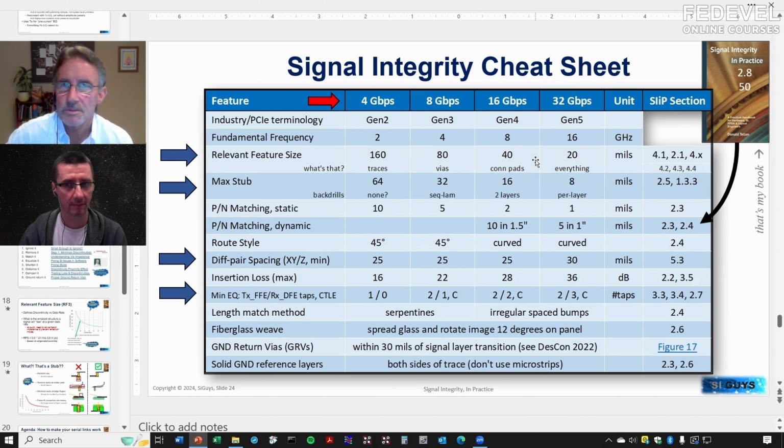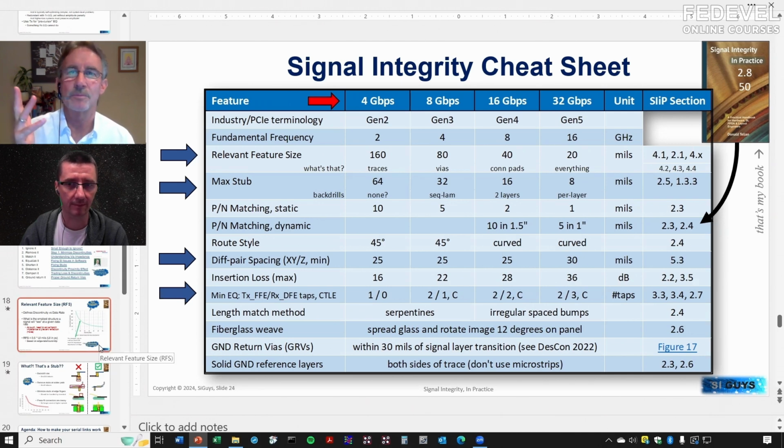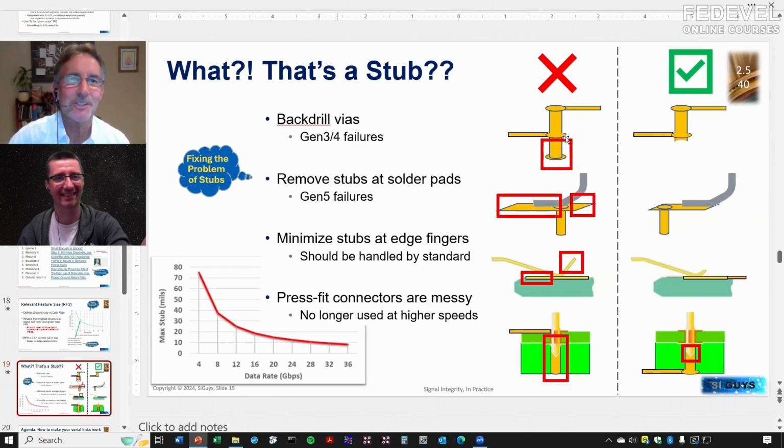So, but everyone's clear on what back drilling means, right? Yeah. Okay, because basically, for example, when we have through hole via, then we can drill out copper until specific depth. Yes, this big fatter drill bit, believe it or not, goes back up and blows away all the copper. So here we are. Okay. And here you have nice pictures. Now this is showing you no, no, no, no, no. Okay. Don't do it like the red X, do it like the green check mark, right?